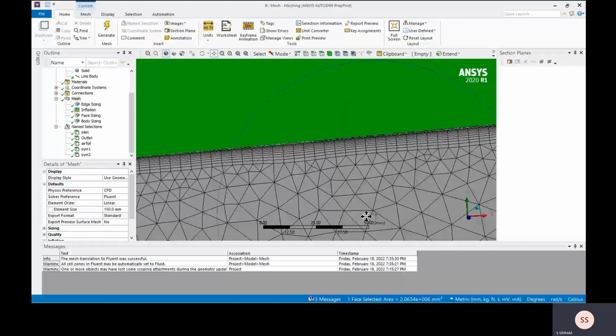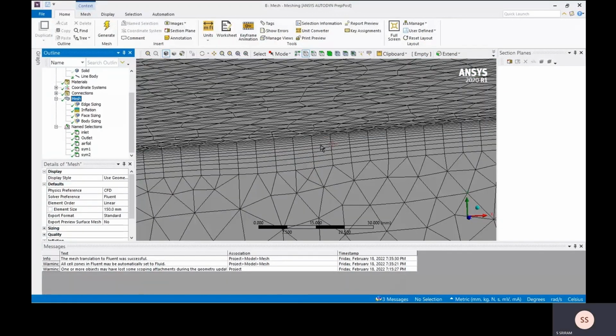The reason we do this is that in an airfoil, all the lift and drag happen along the boundary layer itself. So we want results as accurate as possible without much error, and we need more nodes in order to get uniform, accurate results that are reliable.